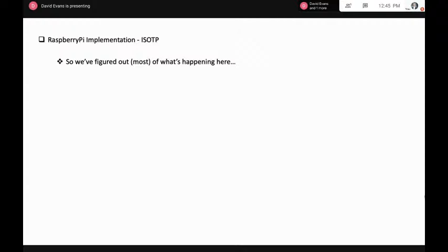It's probably also worth mentioning what I said earlier about ISO-TP dictating the rate at which these messages should be sent. When it comes to trying to do this, the LCD device, which is effectively sending the flow control messages, can be quite forgiving about timing, because ultimately the Raspberry Pi is not a hard real-time system.